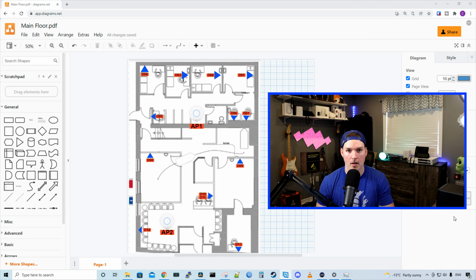There are a ton of different cable labelers out there. There's no real right answer of which one to use, whichever one suits you the best. The main thing is to make sure that we label it at both ends so it makes troubleshooting a lot easier.